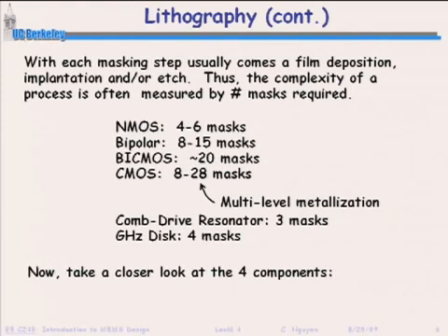For the number of steps that you need to do some of the more advanced CMOS processes, that include all sorts of things now, not only getting small features and using ALD gates, but also introducing stresses into the structures to get higher mobility and that sort of thing. There's a lot of technology going into CMOS here, and they are very complicated processes.